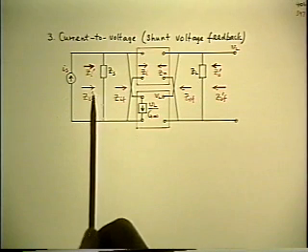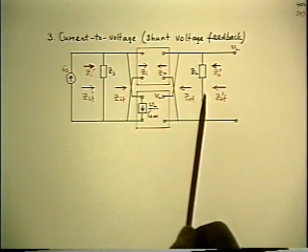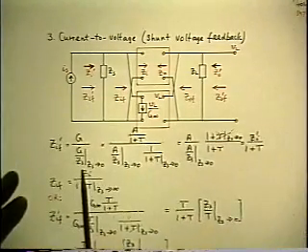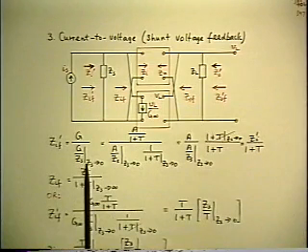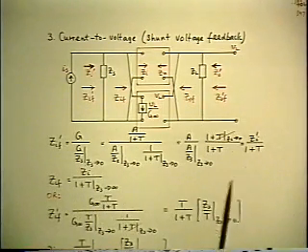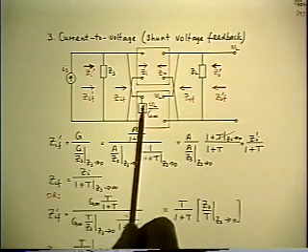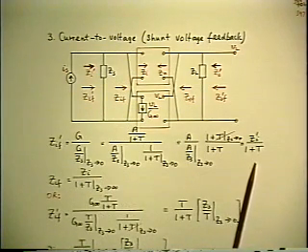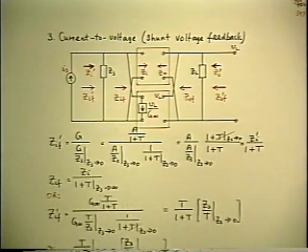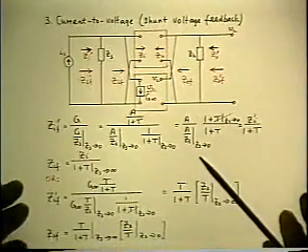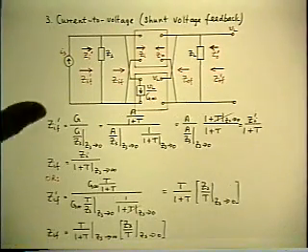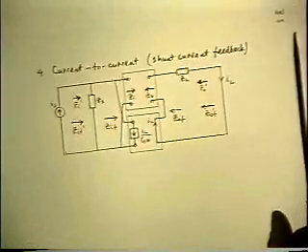So the new formula that we need for the input impedance is exactly the same format as the original formula for output impedance, except we substitute ZS for ZL, and all the corresponding results are the same. Namely, shunt opposition feedback or shunt current feedback lowers input impedances. So that's type 3. And finally, type 4, there's nothing new at all.